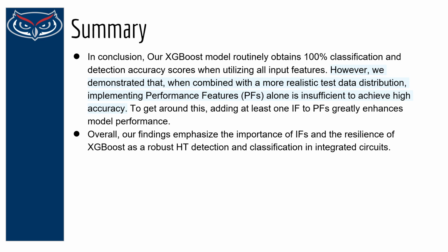Functional Trojans are realized by the addition or deletion of transistors and gates, and parametric Trojans by modification of wire thickness or other circuit parameters. Trojan cells can be placed loosely or tightly in the physical layout, in white space or space created by displacing the cells of the main circuit.